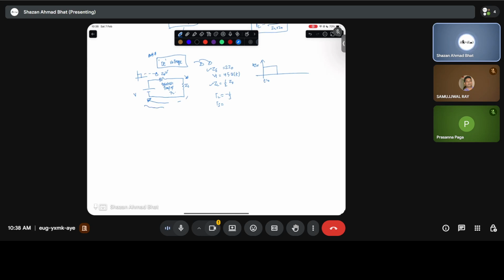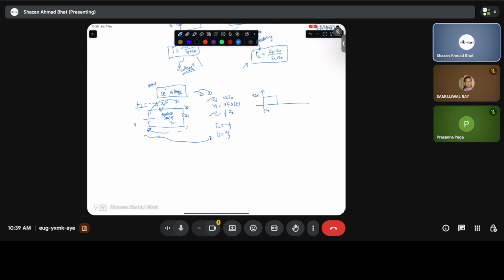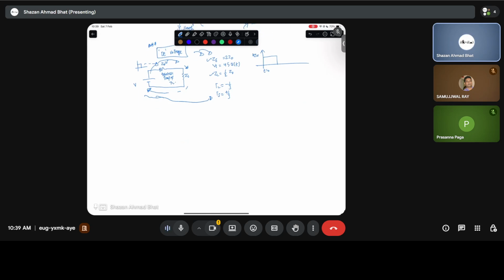And the reflection coefficient from the source end will be such that it will go back to the load. So that reflection coefficient will be equivalent to plus 1 by 3. You can compute it simply by using this particular equation. Okay. And now what is going to happen? Now you're going to compute V1 plus, which is basically the voltage at time t equals 0.